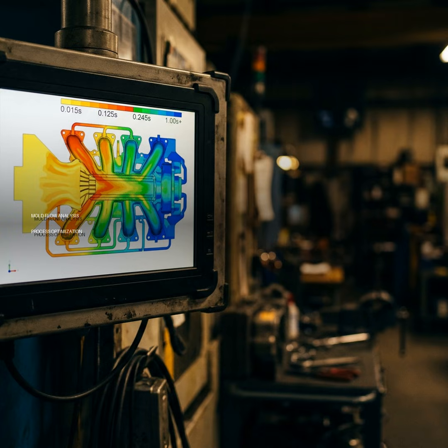Yeah, that's exactly right, Mia. Look, DFM is crucial. It's your foundation. But mold flow analysis, or MFA, is like your crystal ball. It's an advanced simulation technique that uses CAE software, like Moldflow or C-Mold, to predict exactly how that molten plastic is going to behave inside the mold. We're talking finite element simulation of the whole process: injection, holding pressure, cooling, even warping.